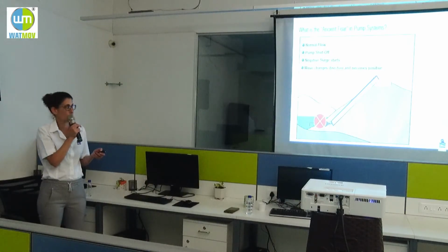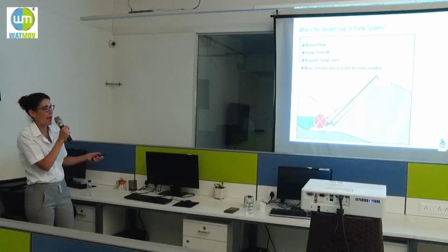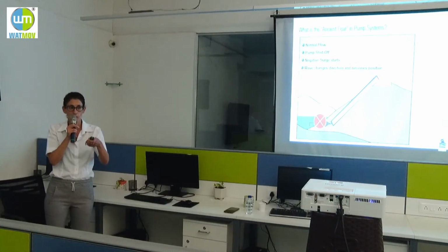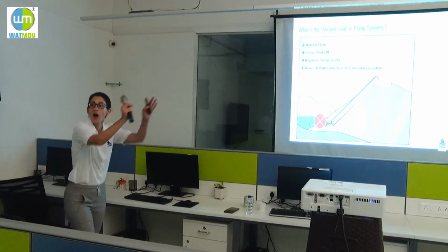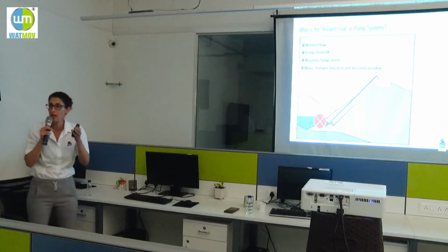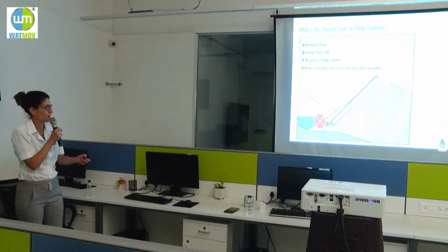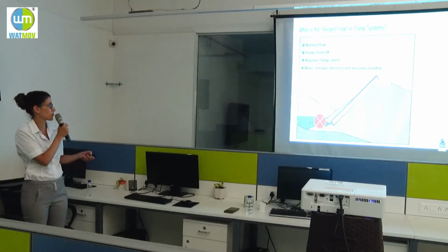And then what we will see, the pressure in the main line, when the water is pushed up, the pressure in the line will drop. This is what we call the negative surge, the negative wave of the surge, okay? Because all the water is pushed up, okay? And the pressure is dropping in the line, okay? It could cause us pipe collapse, okay? So we need to treat it.